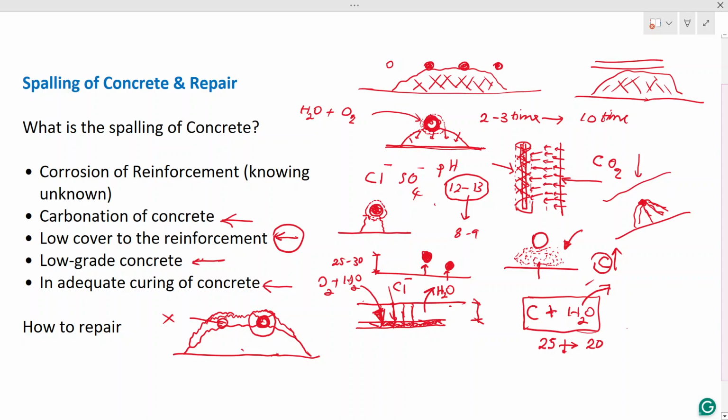You have to keep in mind that when you do this kind of repair, you must have a support. Removing one reinforcement bar in a slab won't cause issues, but if you are going to remove a certain number of reinforcement bars, you must support the slab before doing this repair, because you don't know the condition of the slab.